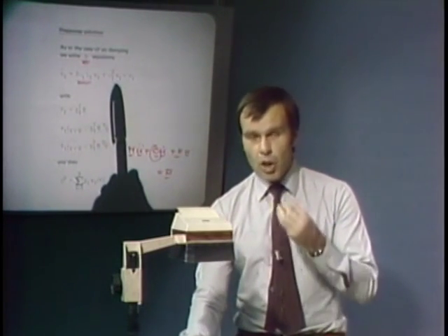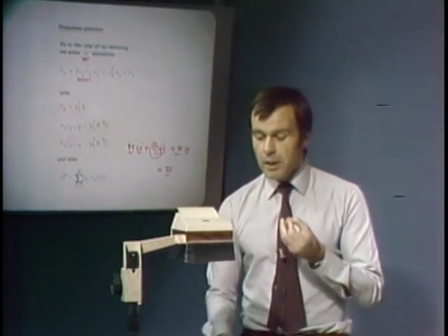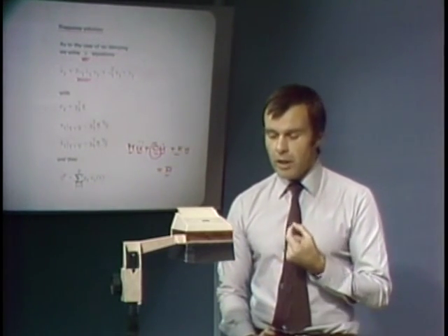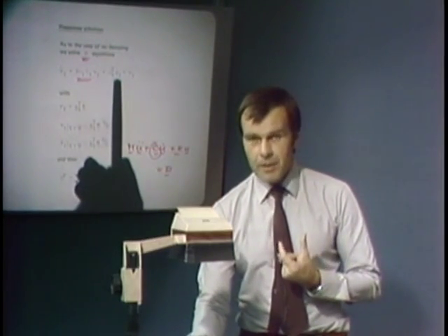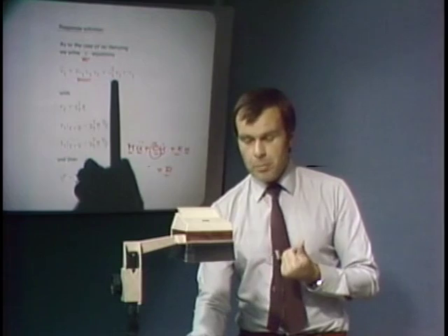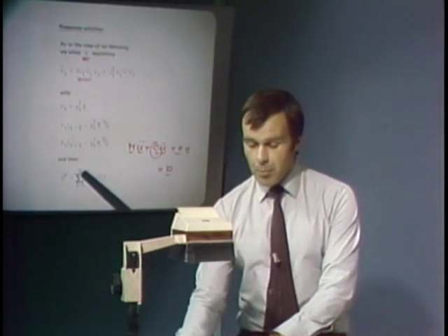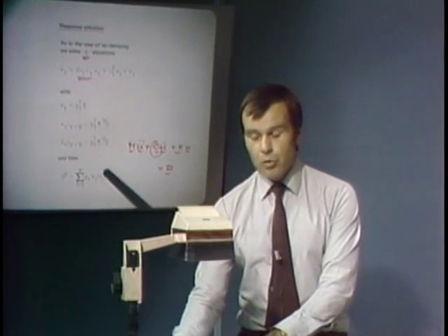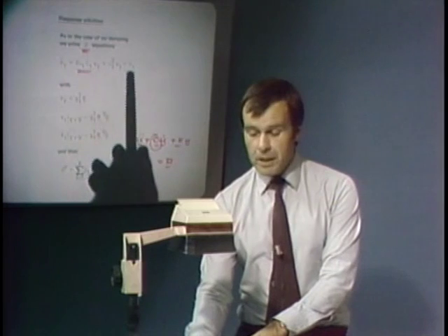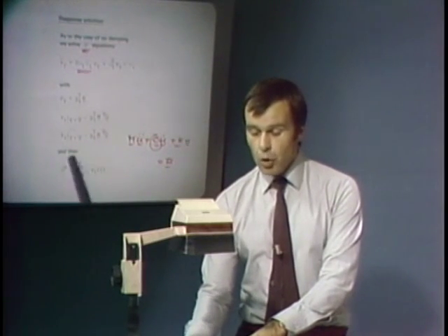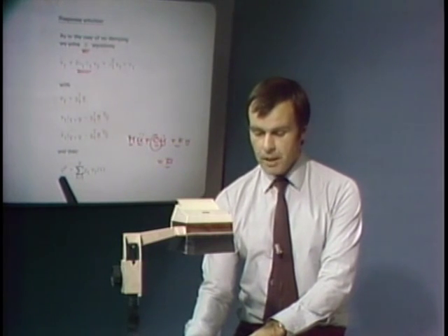The important point is, once again, that all we have been doing so far is to make a change of basis from the finite element coordinates to the generalized displacements xi. That was the first step. The second step was that we are neglecting the modes p plus 1 to n by only solving the first p equations here and using this as an approximation to the actual solution.